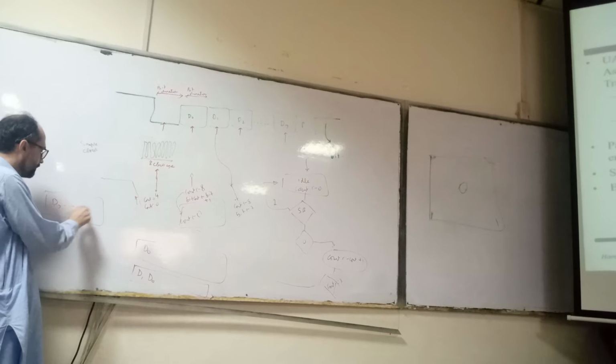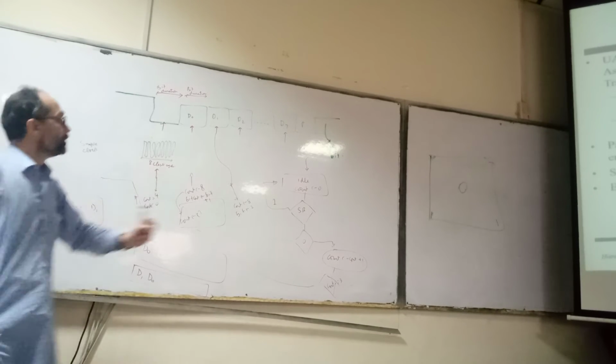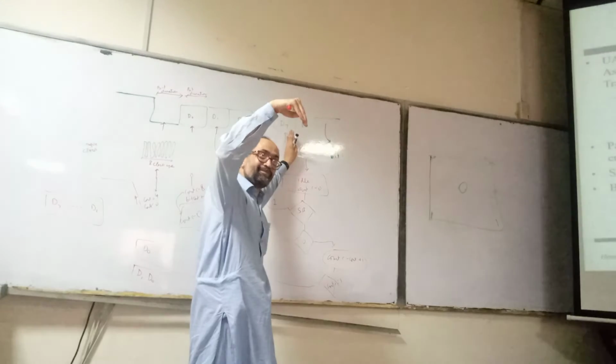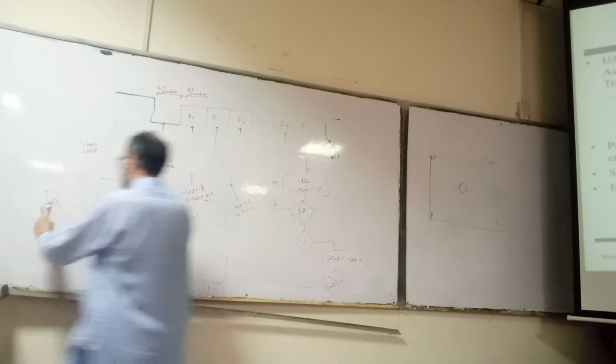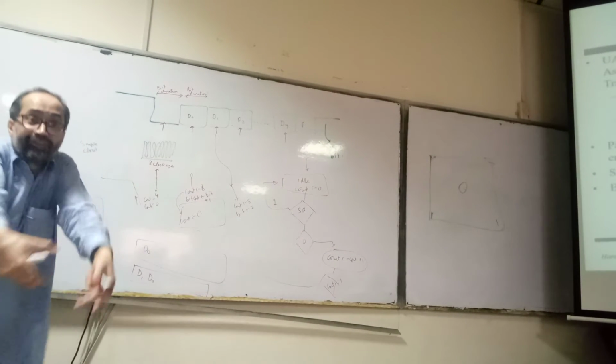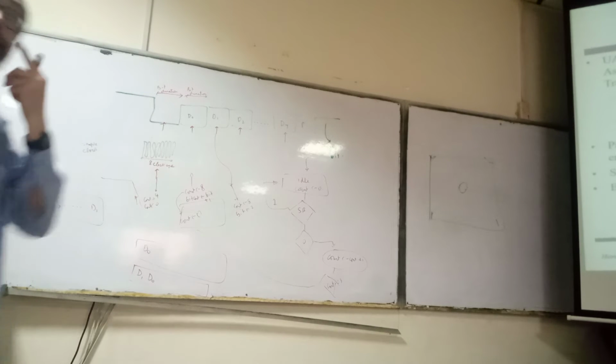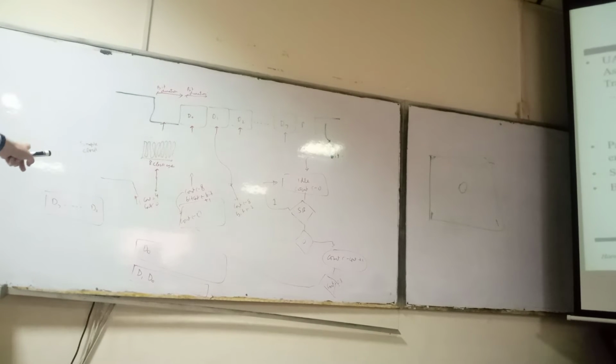D7, D7, D0. Up to D0. So in this case, now we have sampled the last bit, and this data is now in the register. So now it has received the serial data and transferred it in parallel. Now the data is 8 bits.